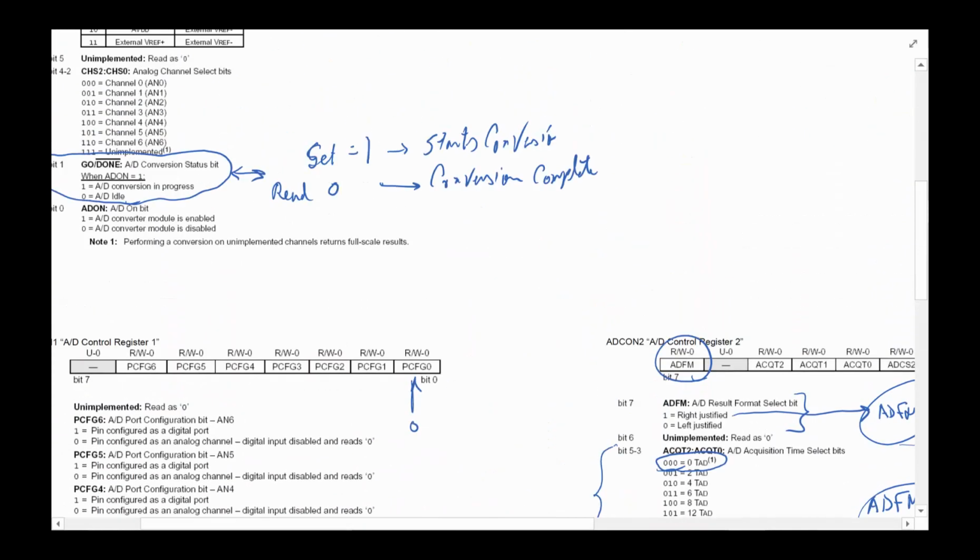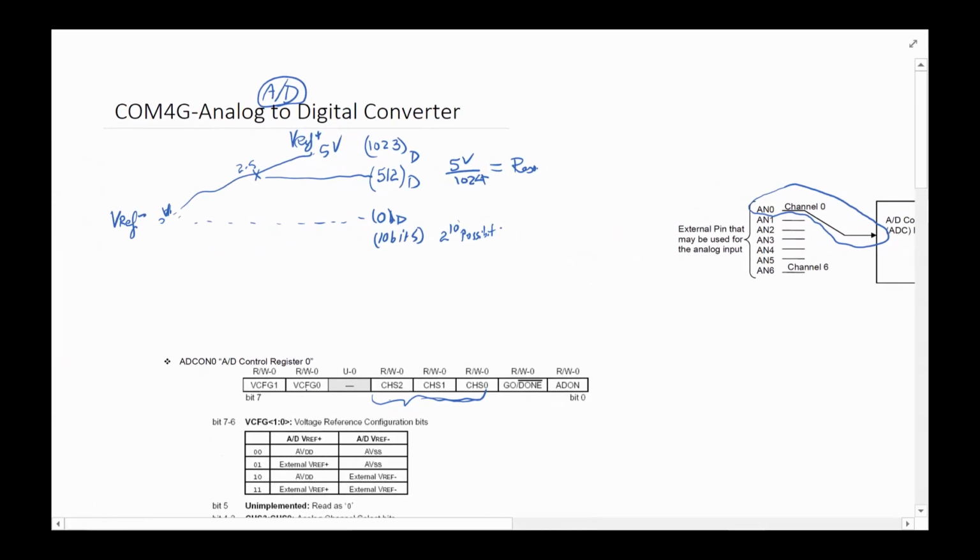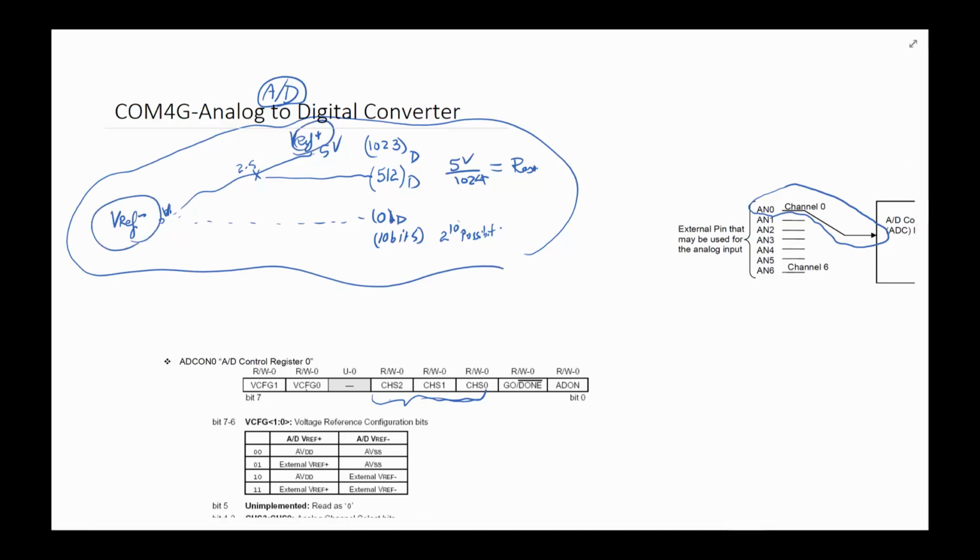So that brings us to the end of the A to D conversion, and all this is doing is allowing you to take an analog signal between a V reference minus and a V reference plus, and give it a specific number associated with it. We can have 16-bit, 24-bit, whatever bit, depending on the processor. But in the case of the PIC micro, we have 10 bits spread over 2 bytes, corresponding to what voltage is being read at the time of conversion from the pin you have selected. And this brings us to the end of the A to D converter overview.